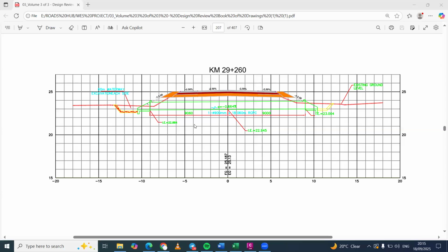Cross sections are also important because they help us define or calculate earthworks. In the previous session, we were able to do QTO, quantity takeoff, which was basically earthworks calculation. There are many ways we can create a materials list, but we focused on cut and fill. The software is able to generate earthworks for you from the cross section.